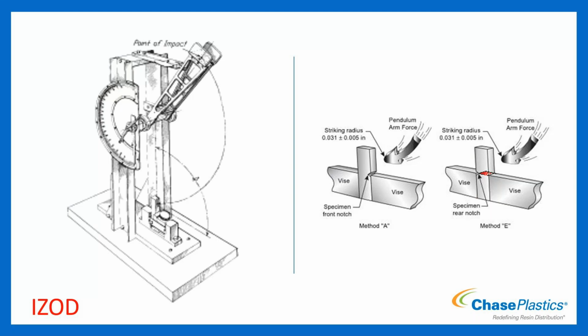The notch allows it to break across it. It basically makes a spot for you to propagate your break. It makes it more uniform, or at least the site at which it breaks is more uniform. So we tend to use notched IZOD as a more uniform value to compare. Your pendulum starts up here, it comes down, and it breaks the part, unless it's a no break, in which case it doesn't break. But it breaks the part, and it measures how much energy was absorbed and gives you your IZOD impact value.